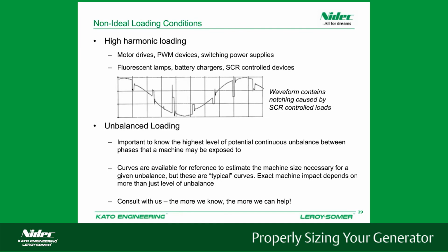So we will continue on with electrical considerations. We have non-ideal loading conditions, such as motor drives, pulse width modulated devices, switching power supplies, fluorescent lamps, battery chargers, SCR controlled devices, and unbalanced loading.